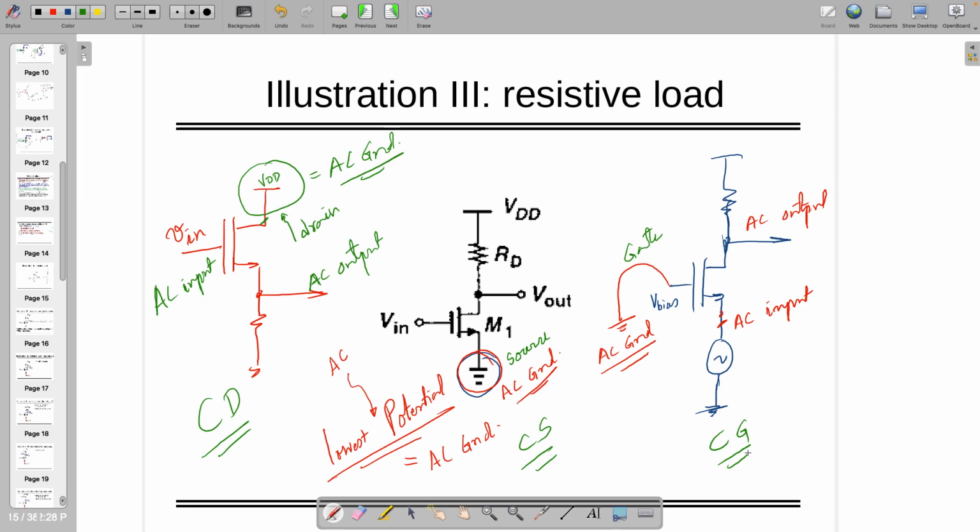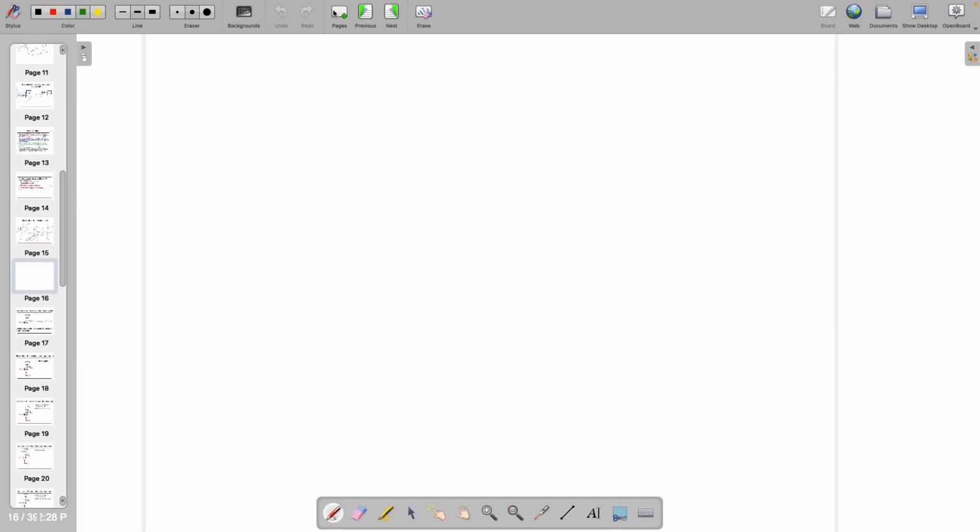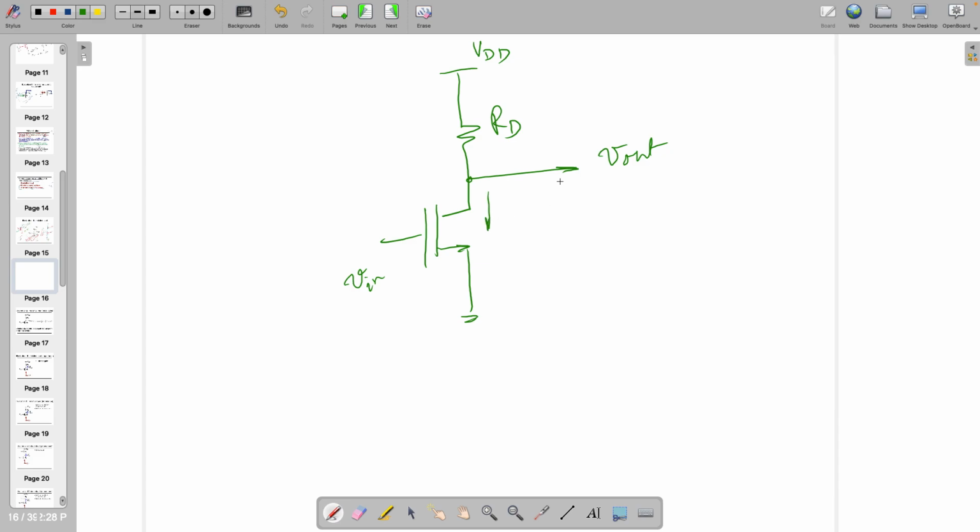So let's assume that you are in common source amplifier which has been given the resistive load. As I told you, you can solve this using some mathematical approach also. If you follow that, what is Vout? What is Vout? VDD minus ID RD, right? You know what ID is. You keep the value of ID and take del Vout by del Vin. That's going to give you the gain.